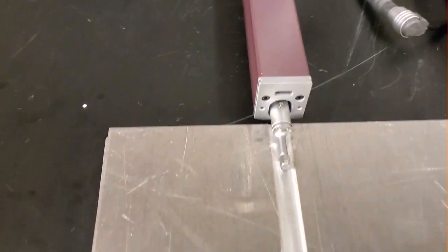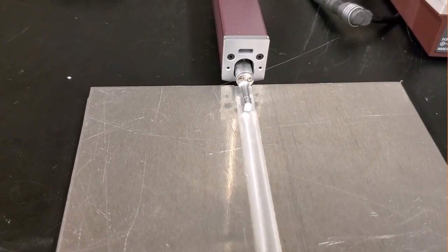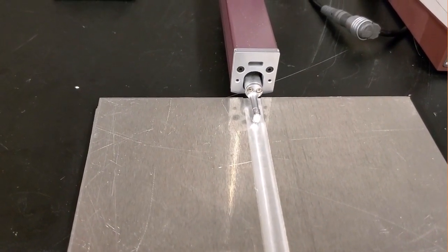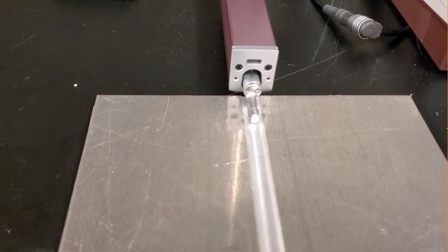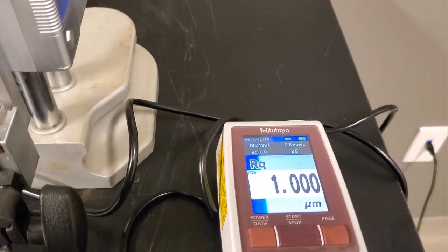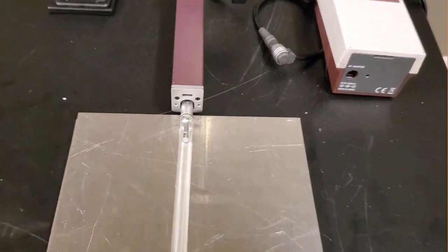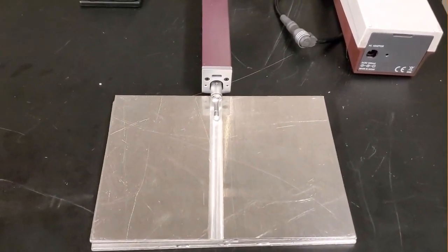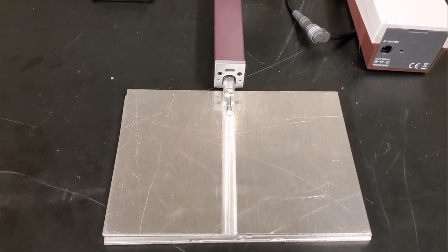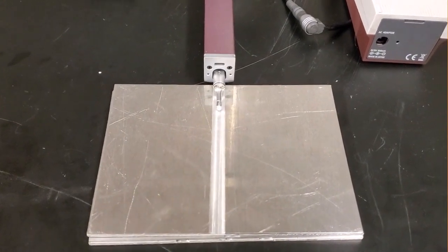As soon as we do that, we see that the probe starts to move along the surface that we want to measure. Okay, and once we have that, the reader will give us the value. And it's always safe practice that in actual experimental setups, we conduct the test over 2 or 3 different spots on the test surface, so that we know we get a good average.